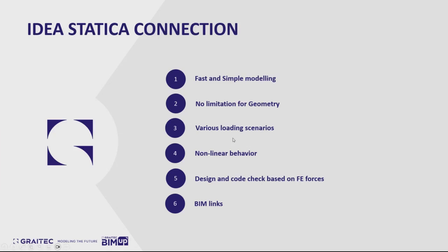There's also no limitation for the loading. So you can have in-plane and out-of-plane forces applied to your connection. It can do nonlinear behavior, both material and geometrical, because it's a full finite element solution. And also, the other important part is it can code check your connection components based on different codes.